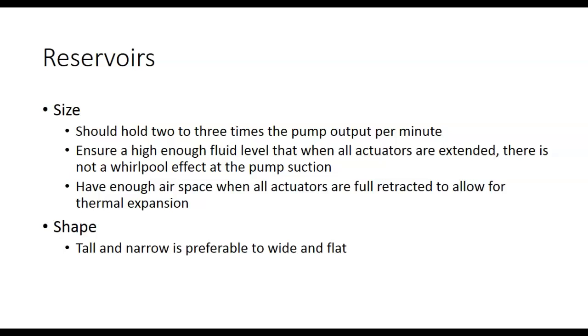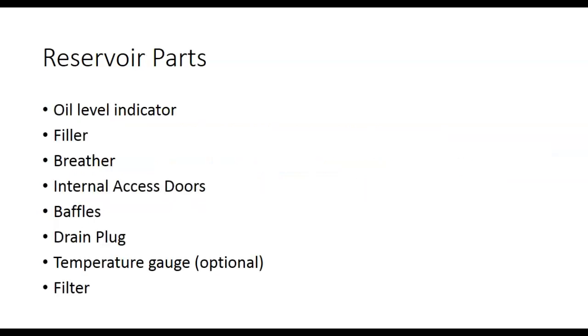Liquids do expand when they heat. It'd be awful if you got in there on a real hot day and your hydraulic fluid started spilling out. Shape: tall and narrow is preferred over wide and flat. Reservoirs usually have oil level indicators. They'll have a filler. They'll have a breather.